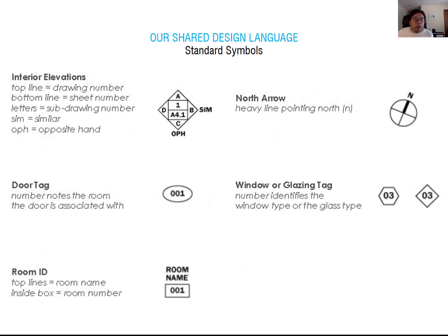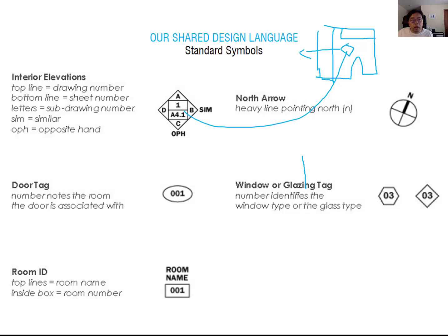Then interior elevation. For example, when you design a bathroom, you have to include the 4 different elevations. So you design the bathroom here, this door, then you have a top here, and this is your sink. Then you have to include this information here, and you need to draw this side elevation, this side elevation, this side elevation, this side elevation. This way you understand the elevations of your bathroom much better.